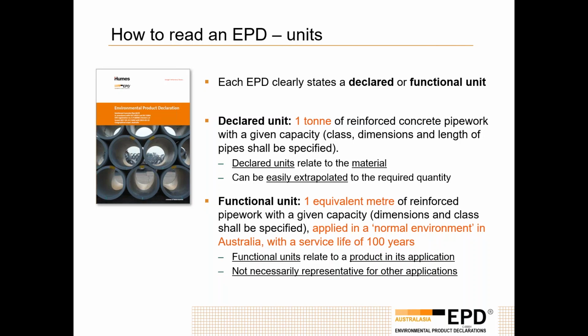It shows you need to look at where it is being applied, because that will impact on the durability. It could impact on the maintenance requirements. And you also need to know the service lives. In this case, 100 years, because again, if you choose an alternative product that only has a service life of, say, 50 years, then you know that you need to replace it in order to get to this functional unit of 100 years.